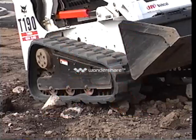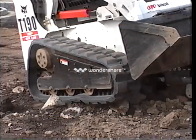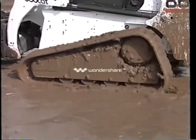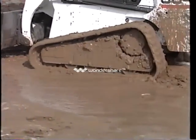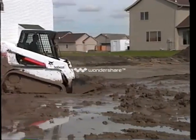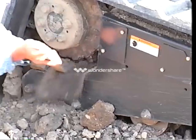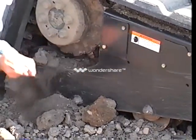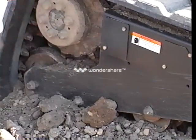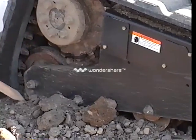Turning on sharp objects can cut through the surface of a track and damage the lugs. A compact track loader works well in soft and wet conditions, but it is important to keep mud and debris buildup down to extend component life. Remember to clean out mud and debris buildup from the track rollers, idlers, and sprocket areas daily. This is especially important when temperatures fall below freezing after loader operation.